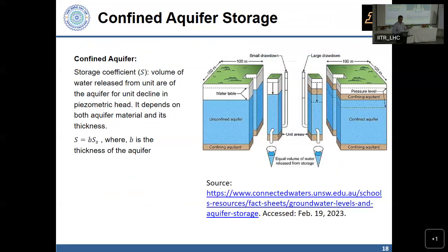For most aquifers, when they are dealing with essentially horizontal flow, we are thinking of flow going throughout the thickness of the aquifer. That is the Dupuit assumption, the essentially horizontal flow assumption. We are looking at piezometric head at one location, and piezometric head at another location. We are interested in knowing, throughout the thickness of the aquifer, how much water I am releasing when, let's say, the water table height falls from one location to the other.